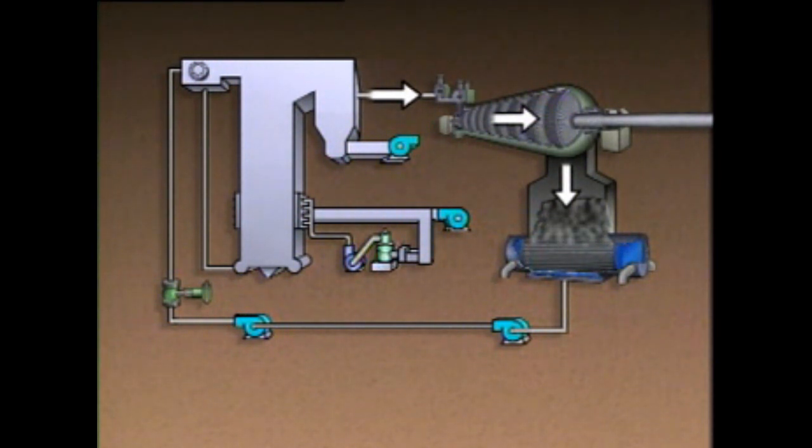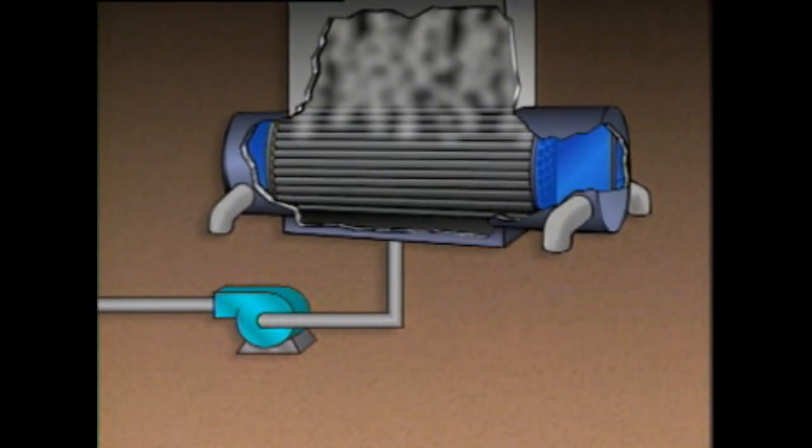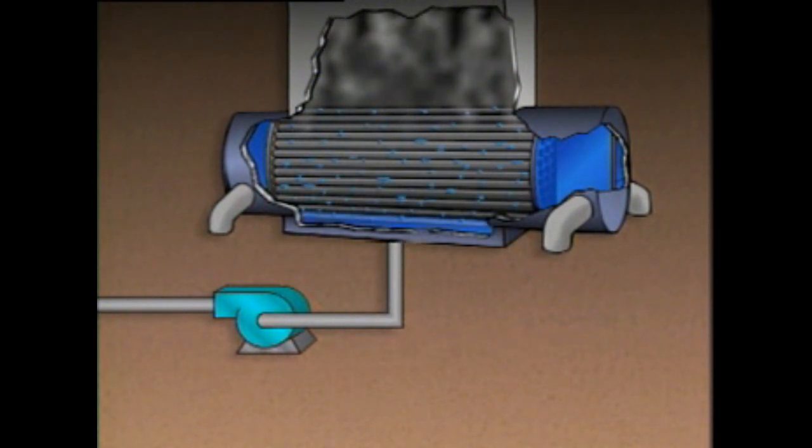As the steam gives up its energy in the turbine and is converted into water in the condenser, the pressure drops dramatically. When steam first enters the condenser, it fills the available space. But as the steam condenses, taking up less and less space, a vacuum or negative pressure is created in the condenser. This negative pressure tends to draw more steam through the turbine and into the condenser. Once the steam is condensed into water or condensate, it collects in the hot well.